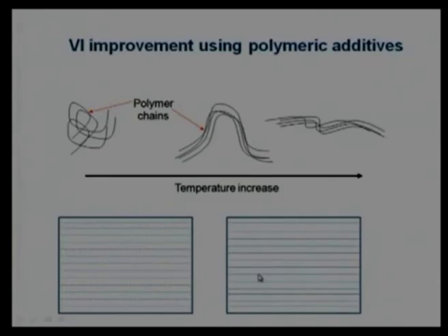That indicates that viscosity is decreasing with increasing temperature. So, on this increasing temperature side, viscosity is decreasing in this way. But as we know, there is another constituent, an additive in this, which will also open up with the temperature and increase viscosity, maybe in this form.